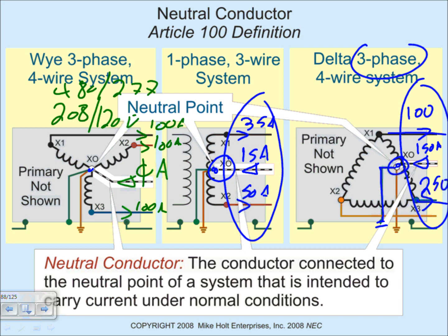Great example: I have a three-phase panel right here, guys. I grab a feeder and feed 10 lights, 10 lights, 10 lights. On the neutral of the multi-wire branch circuit, I expect to get 0 amps, or as close to 0 as you can. Because of harmonics you'll get some amps, which is a different story. But if they were resistive heater loads or completely inductive loads, you'll get 0 amps if they're balanced.